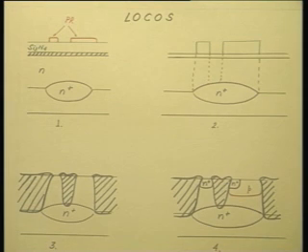Si3N4. This has to be chemical vapor deposited silicon nitride, stoichiometric silicon nitride. The plasma deposited ones do not work very well. So, most people use chemical vapor deposited silicon nitride. So, on top of this you have chemical vapor deposited silicon nitride, and then you have a photoresist pattern on that. That is, some regions of this silicon nitride are protected by photoresist. So, this is your first figure.